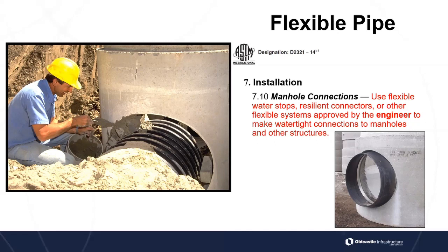Maybe what he's laughing about is he knows that if that pipe were to deflect, if it gets loaded, then that pipe's just going to crack that grout. You're going to have issues with the water leaking there. That's why they want you to use this flexible connector, like a boot, a rubber boot or something, because we know that pipe's going to deflect even a little bit, right? Up to 5% is acceptable.